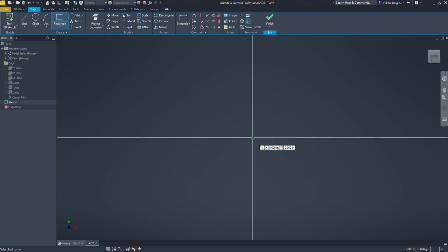Now hover your pointer over what looks like crosshairs, and you'll see there's a little dot there. That's your origin, your 0, 0, 0 XYZ position in space. Now be aware with Inventor, you can actually delete that, and there are some benefits to that, and some challenges if you do delete it. So I would recommend you try not to delete it. But go ahead and hover over the point when it turns green. And by the way, the colors here might vary on your release of the software, and I'm going to go through in a little bit how to change that.